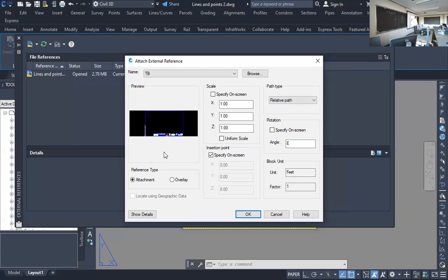If you drew your title block to scale, you're not going to scale it at all. It's going to be 1-to-1. Almost exclusively, the stuff is going to be one. You're not going to want to scale stuff up and down. And the base points for external references are always 0, 0. You want to insert everything at the same location. That way, if we have all of your buildings as separate entries, I can take all of your surveys, put them together and make one big map of the campus. If I insert everything at 0, 0, and you put your stuff on state plane coordinates, correct?